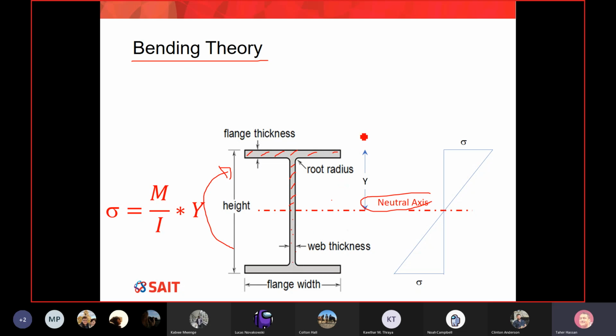What happens here, the beam theory says, when we apply a bending moment, so I'm going to show you a side view of your beam. If you draw a straight line on the side view, I'm sorry, my line is not really very straight, but this is how the cross section will look before the load. What if I apply some load? Beam theory says this plane will rotate linearly. You can see it will still be a plane, but it will rotate due to the bending moment. What is this picture here? Simply, that is the side view of your beam.